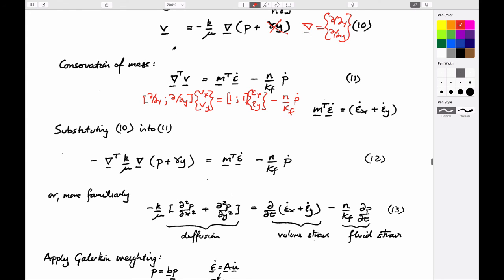so in terms of this, this would be the continuity equation. We would just change in velocity in the x direction with x plus change in the velocity in the y direction with y, which is our standard continuity term, usually equals 0. But in this case, it doesn't equal 0. It equals epsilon x plus epsilon y, just from this term here, which is actually the volume strain, minus porosity times the bulk modulus of the fluid times the rate of change of pressure with time.